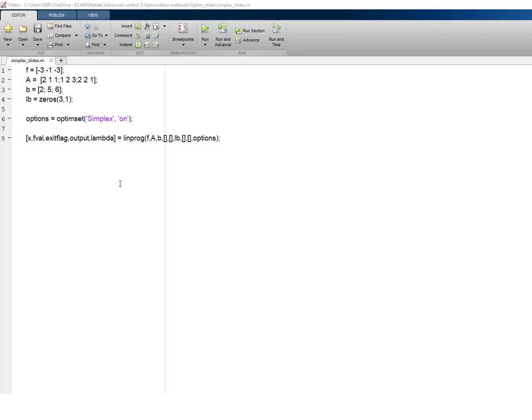Well, here we can again check using MATLAB. So this is the objective function that we had obtained when transforming the maximization problem into a minimization problem. In MATLAB you can still use inequality constraints as long as they are inequalities of the type smaller or equal, which is the case, so you do not need to go to the standard form.